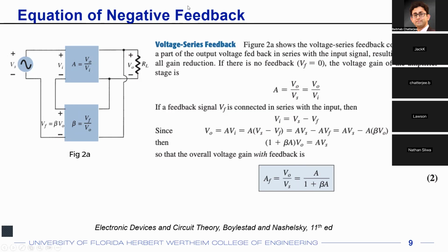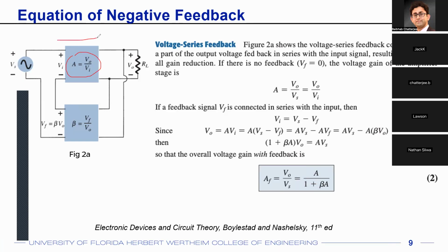All right. So remember that your gain, now this is an important conclusion. Your gain with feedback is A, which was your gain without feedback. Without the feedback, you only had the op amp, or you only had the feed forward path, which has a gain of A. Now with the feedback, you have divided it by 1 plus A beta. So your original gain has reduced.